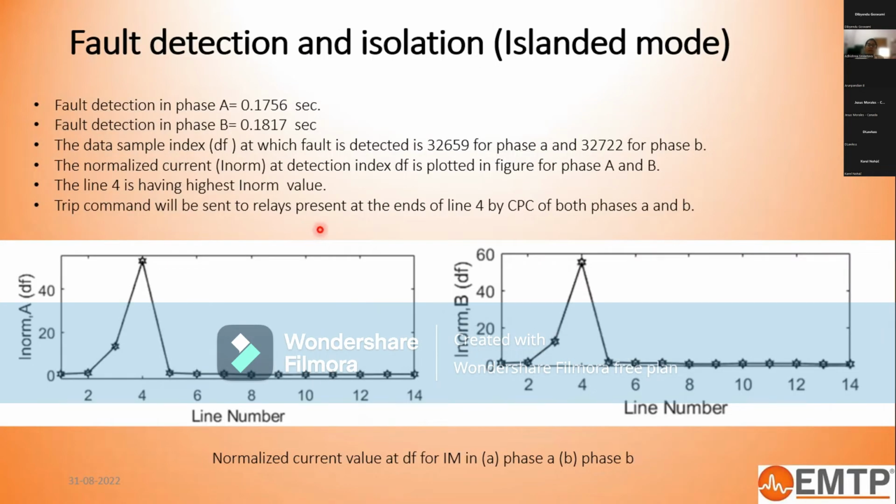Now, after understanding the basic application, a little bit I would like to explain what our motto was. When we change the relay setting parameters, the problem was that whenever we have a change in mode, that is, we switch from grid connected to islanded mode, we have to change the relay settings. Also, if we change some mode of operation, like the DG penetration level, or some lines are out of service, everything impacts the overall short circuit level of the network. So for every case we need some relay settings, and an automatic update of those settings is required.